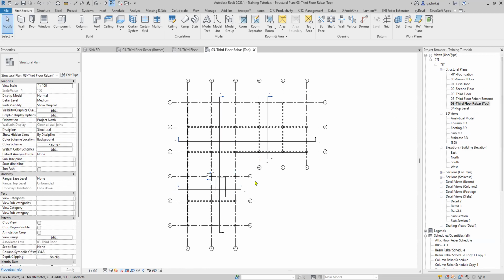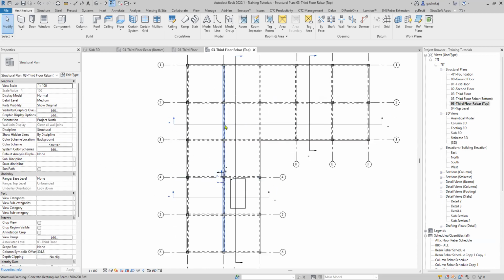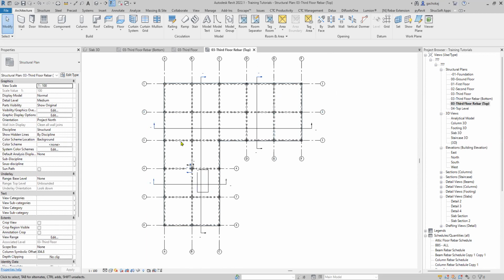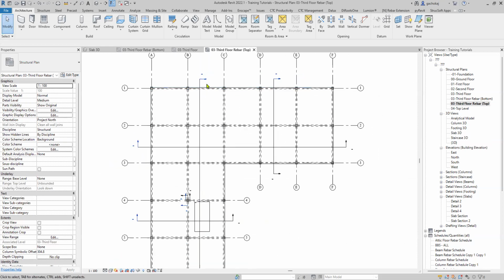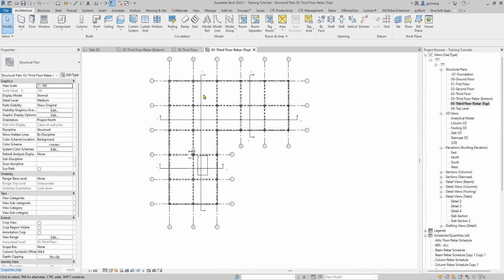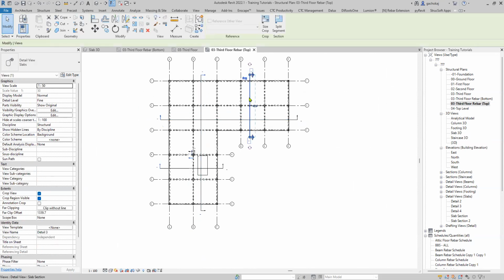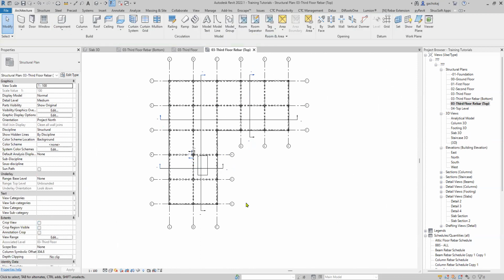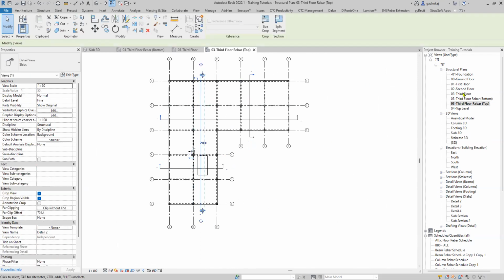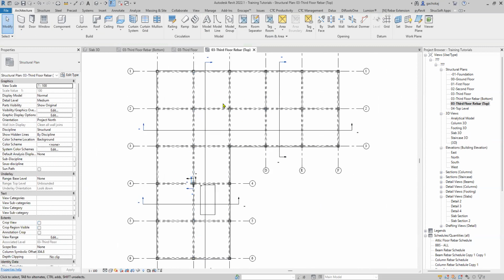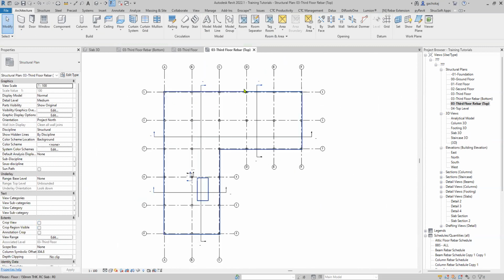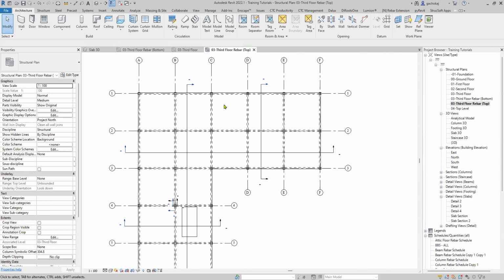And then just like we did for the bottom bars, we'll do view and obscure so that we are able to see our reinforcement on our floor plan. So we'll still do our reinforcement in sections just like before. We might not have to cut as many sections as we did for the bottom reinforcement, since we'll try and use the same sections that we used to do the bottom reinforcement. If we need any extra, we'll create. But for now, let's try and use the ones available.